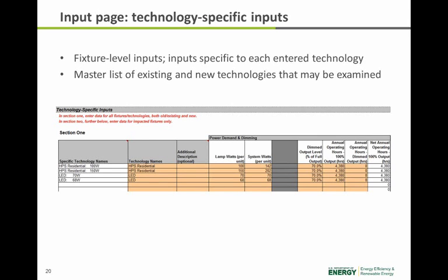But as my two examples showed, there were dramatic maintenance savings going from HPS to LED, and in fact that provided more financial savings than the energy savings. So the person that asked the question is certainly right. The maintenance is quite low with an LED, but there still may be some unexpected maintenance or some cleaning required.